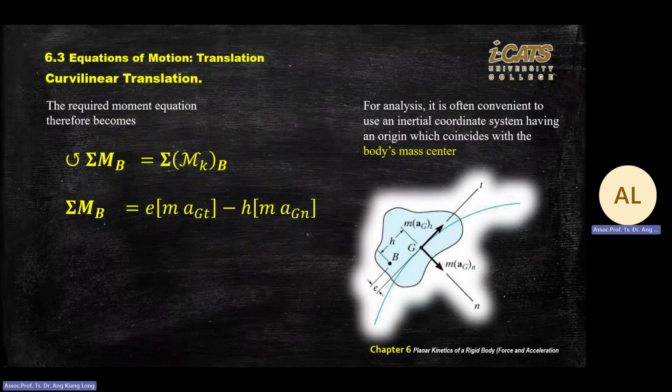Okay, solution 1 is using these three equations. Solution 2 is using the free body diagram and kinetic diagram. I know we are overshooting already. So we are using this equation, sum of forces equal to ma. We are focusing on the moment to solve the unknown. Meaning on the left, you only look at the moment of the force, equal to the individual moment referring to the center of gravity, the center of mass there.